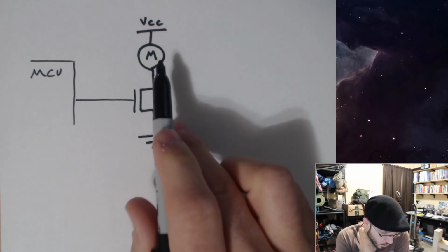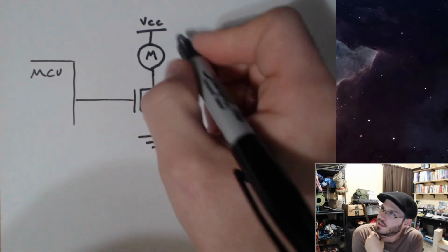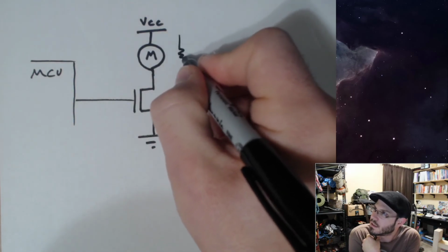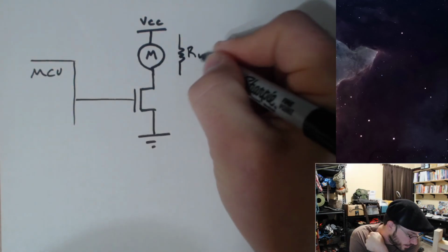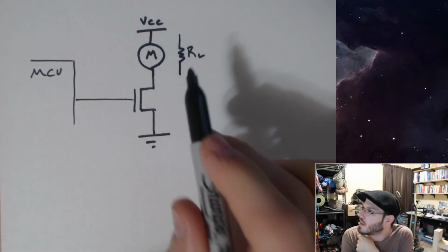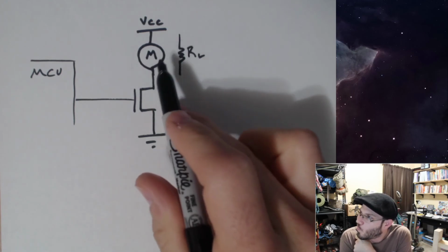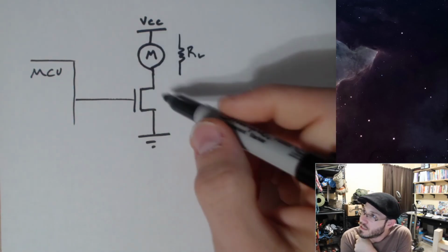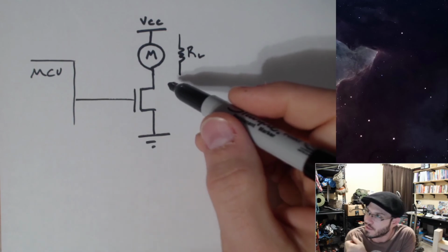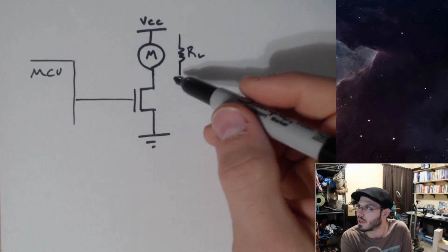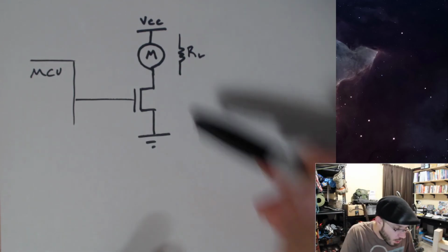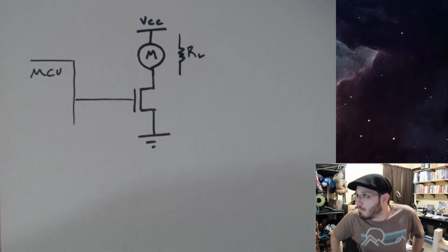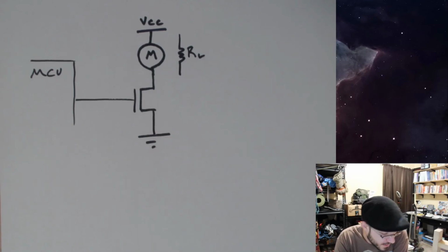Okay, so this motor is obviously a resistance. It is acting like some type of load. It's got some resistance. The motor is the one that's limiting the current through this, and we want to turn the motor on and off. This is a very typical switching circuit that you would encounter in 346, 347, 447, or in the future. There's many things that are going to look like this, so it is a good example.